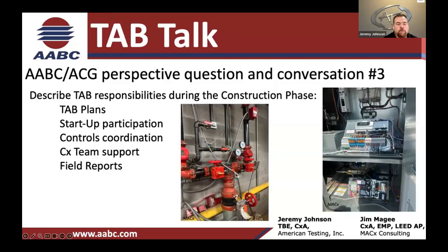That's a good foundation to start with, but ultimately, as you get into it, sometimes you also have to develop niche plans as a result of the construction phase, right? Balancing world, 101, right? We balance by system, right? Jim, they don't build the building and turn it over by system, do they? This is crucial too. You talked earlier about integrating with the commissioning, and it's the same thing. We don't necessarily have to have an entire building if we can start with complete systems. Exactly. And come back around to the holistic part of it. But what kills you is the phasing that divides it up, adds dampers and so forth.